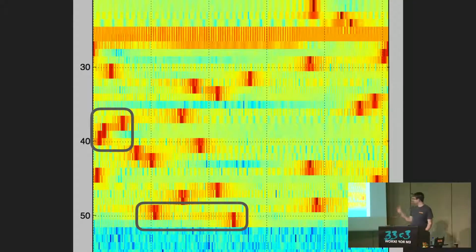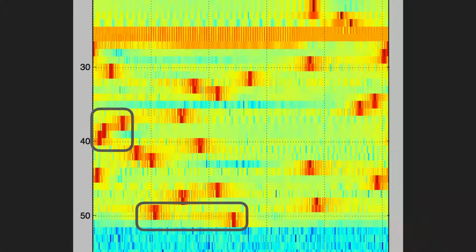If you look at rows 39 and 50, you can see that visually it's almost impossible to tell which of those 2 readings represents the symbol. You see there are 2 different values that are really powerful. That's the result of basically half of the samples from chirp n, and then half of the samples from chirp n plus 1 winding up in the same FFT. So when we do it, we get those 2 components in there, and it's really ugly and hard to work with.